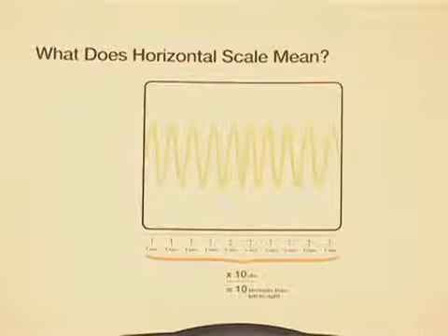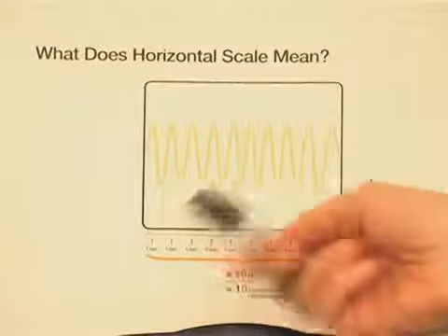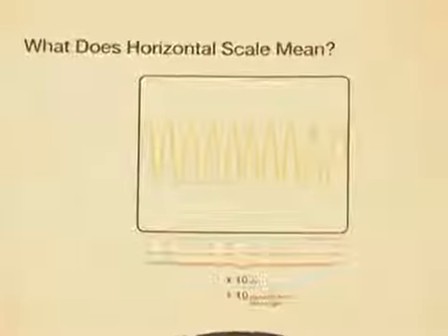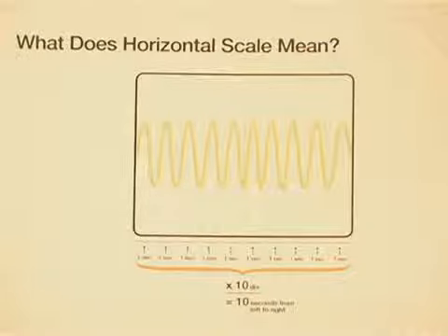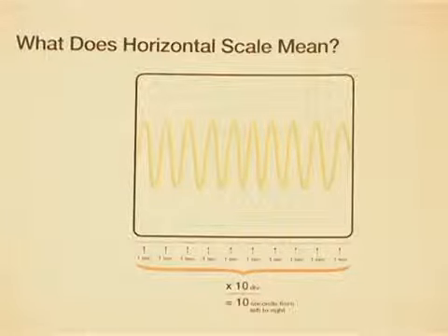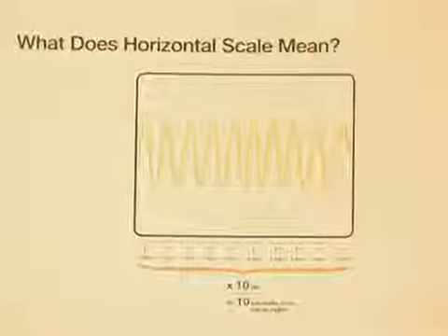And horizontal scale is expressed in seconds per division. So if you have 10 horizontal divisions available on your screen and you have your scope set to 1 second per division, that means you can fit 10 seconds worth of data on the screen. Oh, that's great. That's really similar to the vertical. Exactly. Just a different... Can you see down on the screen also? Yes.